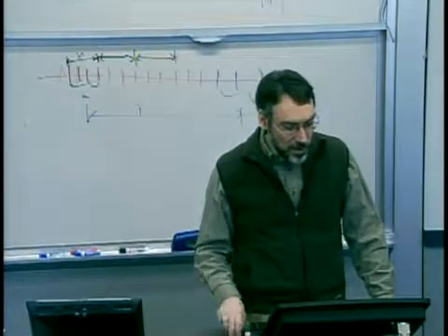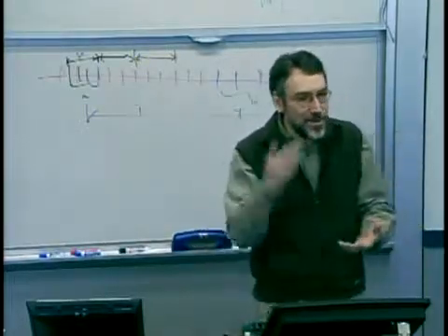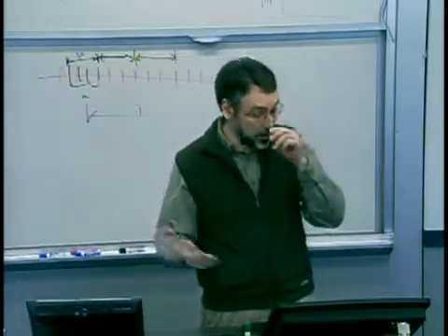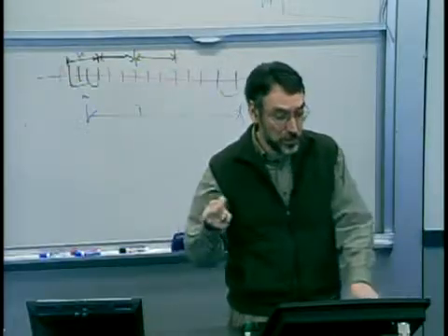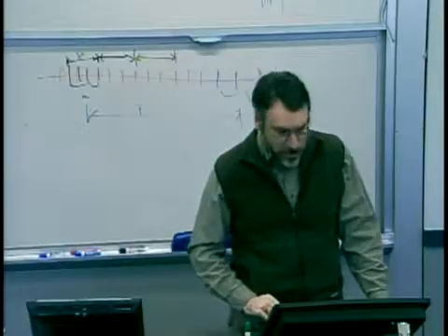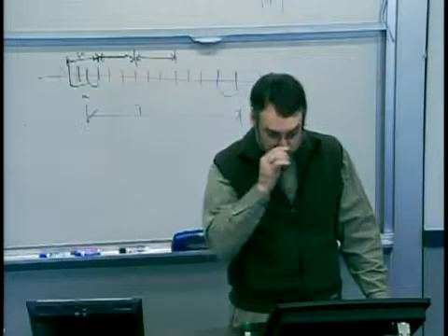The problems are, yes, sample size, I need n more than 1, and very often I may be measuring every one. So I'd like to get to some control charts that might be able to either react faster, a shorter average run length, or be able to utilize the fact that you've got more data and I can have this faster time response.